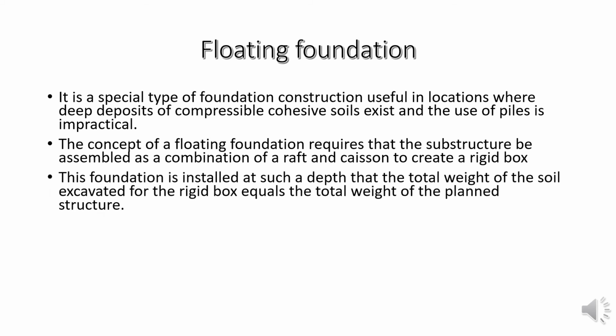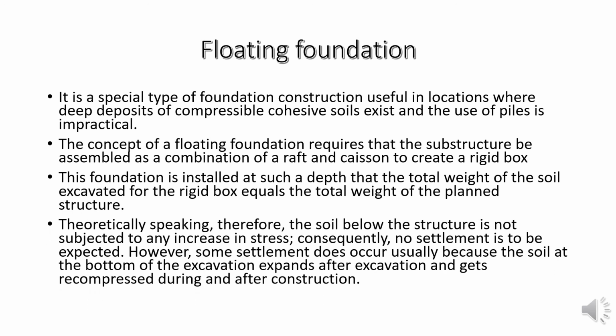This foundation is installed at such a depth that the total weight of the soil excavated for the rigid box equals the total weight of the planned structure. Theoretically speaking, therefore, the soil below the structure is not subjected to any increase in stress. Consequently, no settlement is to be expected. However, some settlement does occur, usually because the soil at the bottom of the excavation expands after excavation and gets recompressed during and after construction.